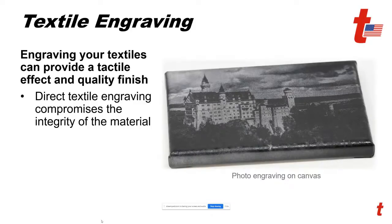So there are not as many fabrics that can be engraved. I would say maybe 5 to 10% of the fabrics out there can be engraved, where all of them can be cut. So you have to understand which ones are going to work best for engraving versus cutting, and we're going to cover some of the more common ones that can be engraved. Most fabrics, just so you know, 80 to 90% of them, cannot be engraved. You can engrave them, but when you stretch the fabric, it will start tearing. The contrast will be low, and it just does not look good. So we're going to stick with the ones that we know work really well.